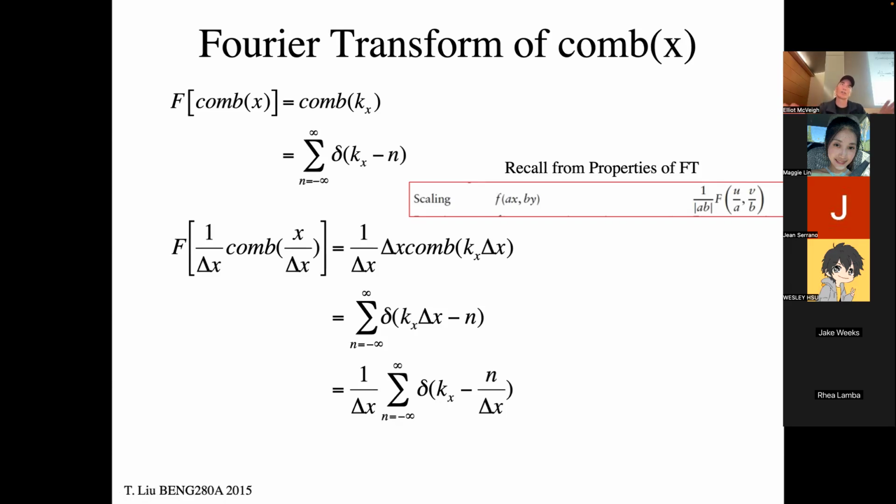And that's the essence of aliasing. I really want to make the separation of these delta functions in the Fourier domain far enough apart that the actual frequency content of my signal doesn't overlap with multiple delta functions. It just stays inside one of those blocks. We'll see that.